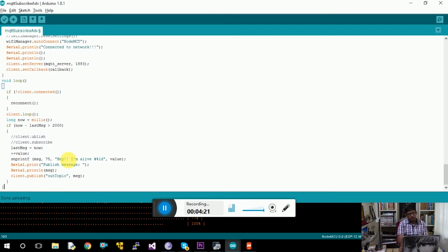Now, when you're using the MQTT protocol, you need to have a callback method as well as a reconnect method. The reconnect method is not essential, it's not like it won't work otherwise, but to stay on the safer side, it is recommended to implement it. In void loop, I repeatedly check whether I have lost the connection or not. If I have lost it, I'll just use the reconnect method again. This will initiate the whole process.